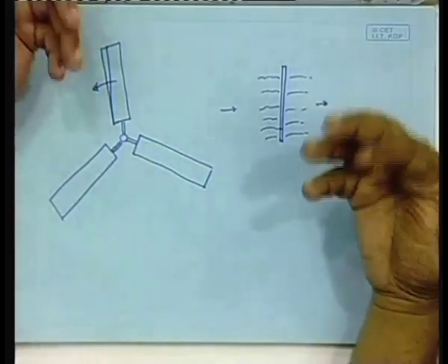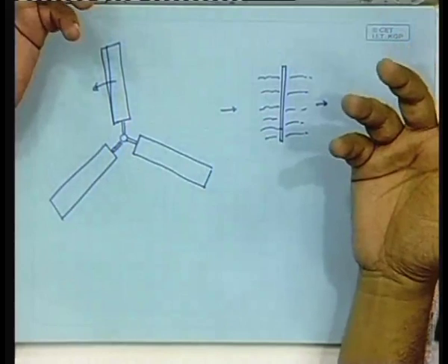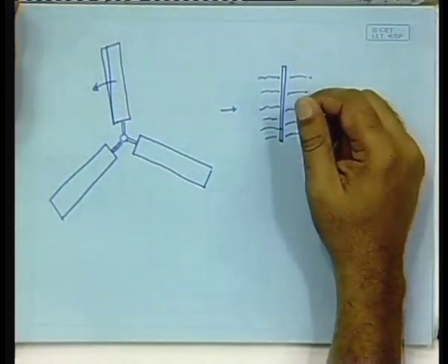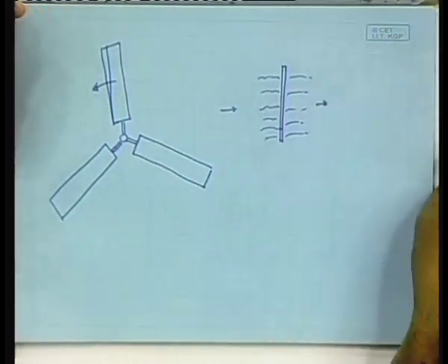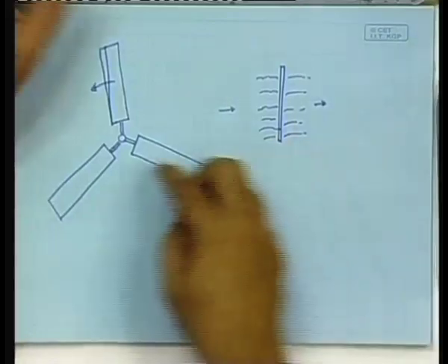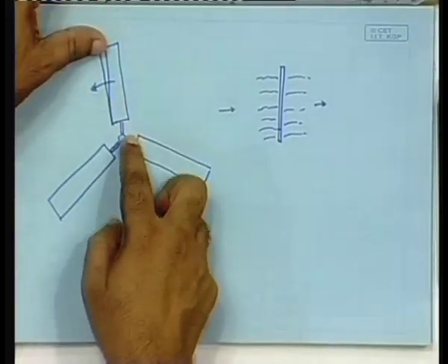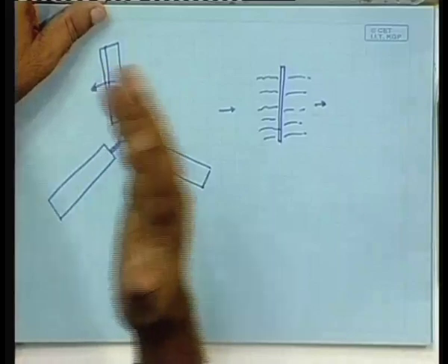So, naturally it will be seeing turbulent wind, and the whole efficiency will go down. And if the blades are so sparse that the disturbed wind passes and the next blade comes much later, then obviously there will be a lot of wind that is passing through without taking part in the energy transfer.